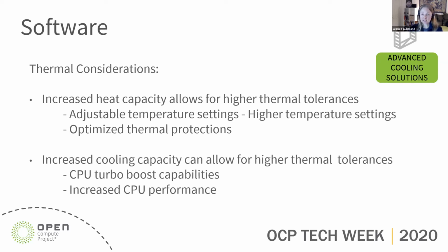There's also, again, when comparing to air, since immersion is a more effective medium in transporting the heat away, it might be an opportunity to have the CPU operate in turbo mode for longer periods of time, just because you're able to create that more efficient cooling capability. And it can also then allow for potentially increased CPU performance as well. So those are some of the thermal considerations.